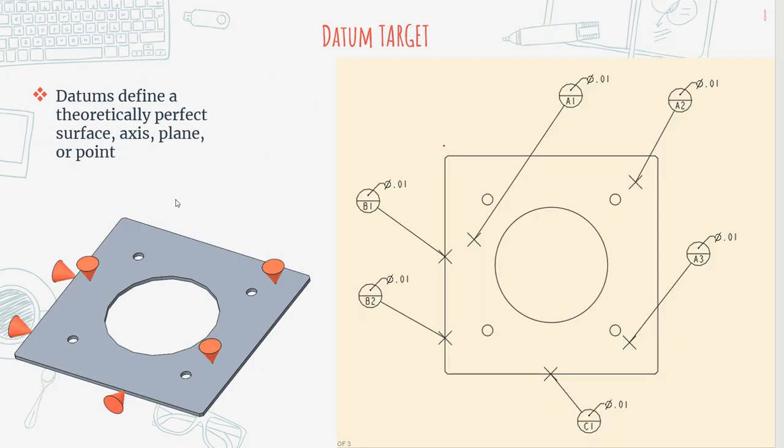And so the reason why we sometimes use the points instead of using planes to define the datum reference frames is because you might have a lot of surface roughness along this location. So maybe you want to define your datum plane precisely at these 3 spots, because you know that these 3 spots are very smooth surfaces.